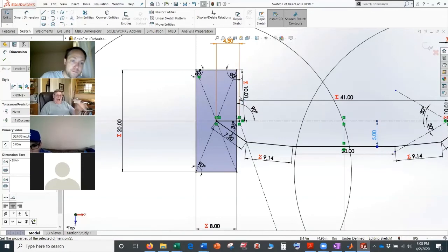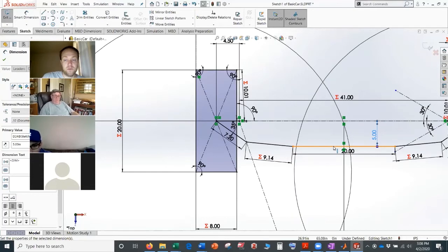Well, for packaging, that's the argument, you could put it in the front. You can totally do either. Baja, we do front steering. And then the angles of the column dictate that too. The steering column? Yeah. If you don't hit your angles, we push it more forward, and it makes your angles smaller on your steering column.